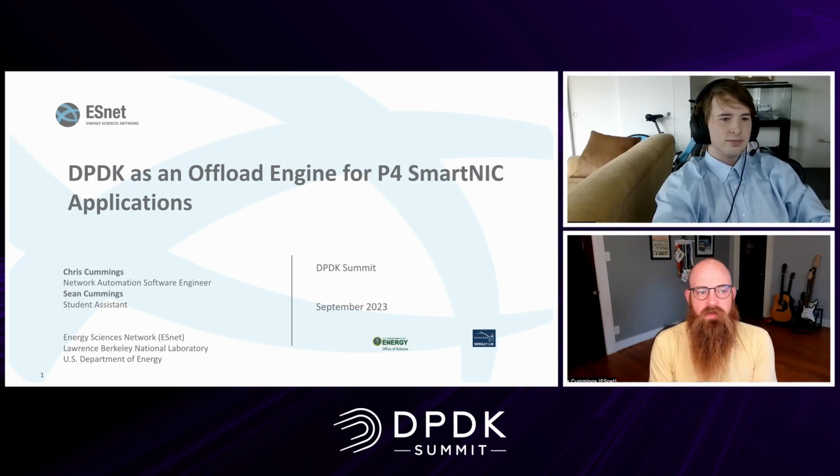The talk title is DPDK as an offload engine for P4 SmartNIC applications. We're going to be talking a little bit about how this summer we, mostly Sean, built an FPGA P4-based SIIT-DC IPv6 IPv4 translator, and how we use DPDK to offload the more complex functions that we didn't want to do in P4 or couldn't do in P4 out of the FPGA.